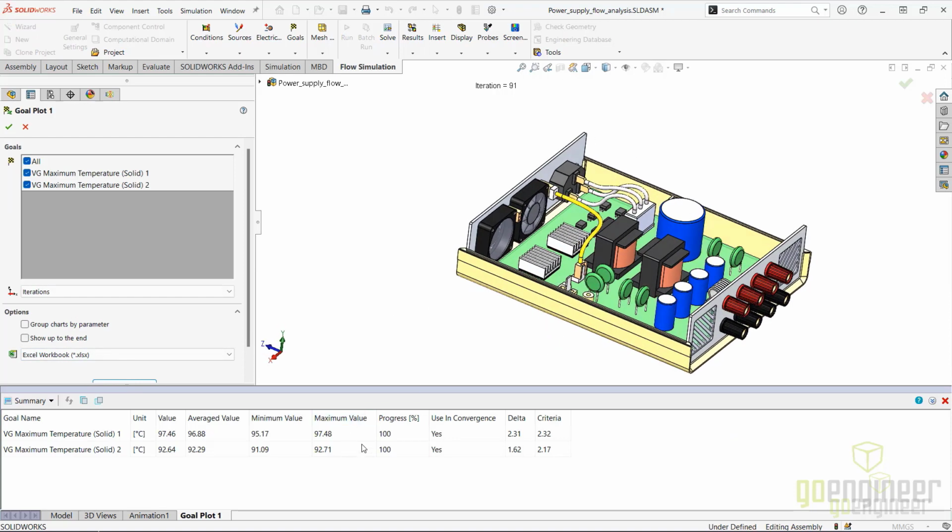So our official results have improved. The maximum temperatures for the ICs are a bit lower at 92 degrees and 97 degrees Celsius. So again, we get a bit of an improvement, but one IC most likely will still fail. There still may need to be some underclocking or power regulation in this case to help out with the extreme climate. Let's close this out.